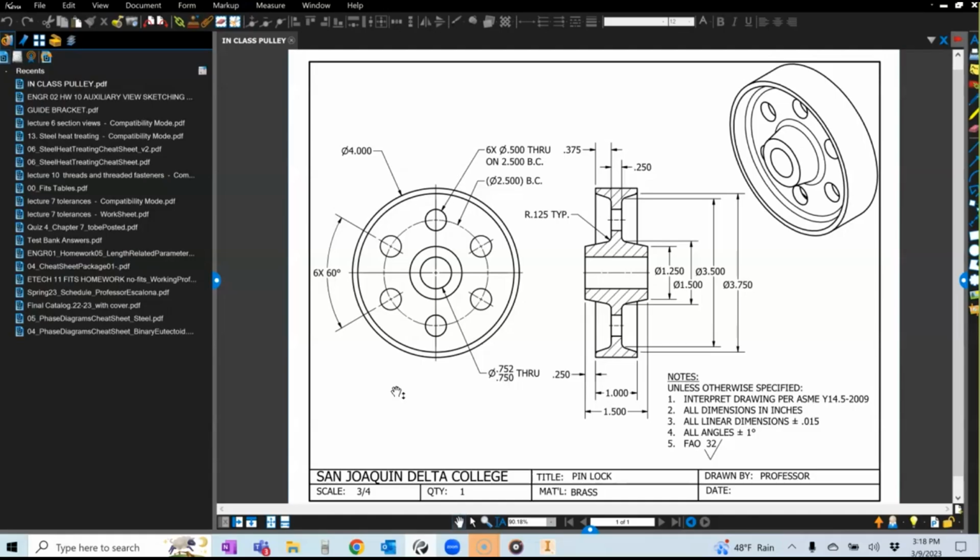There is a command that is called revolve. So you're revolving around. The only thing that you need is a sketch and an axis to revolve around, right? You have a sketch over here and you revolve it around the axis. So the hardest part of this drawing is to come up with this sketch and then revolve it around this axis. We generate something like this. Then make a couple of holes and pattern those holes and you're done. Right, it's not too bad. You just have to do this revolve. Let's try to do it.